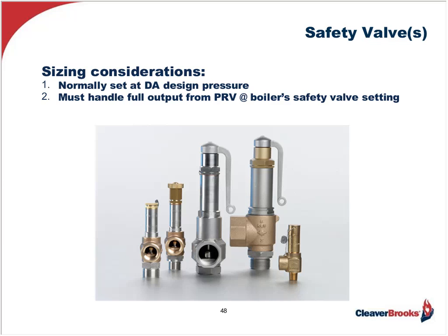Of course, they are there to protect the vessel from overpressurizing should the PRV fail open and/or excessive amounts of high-pressure condensate enter the tank, causing its pressure to elevate. For sizing purposes, these valves need to have enough relieving capacity, which includes the area and the diameter, to account for the PRV failing open and the pressure controls on the boiler failing.